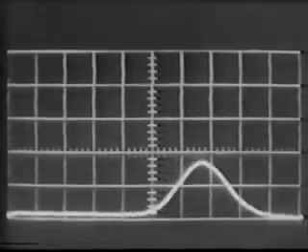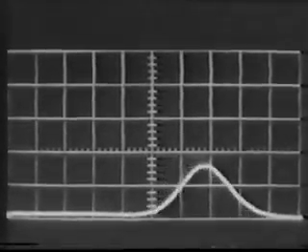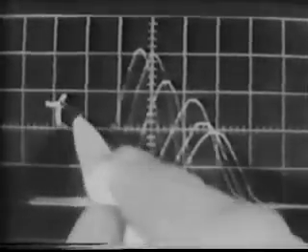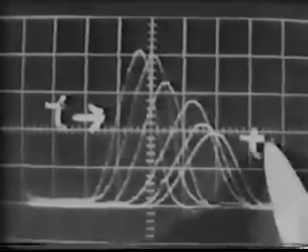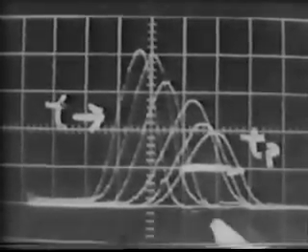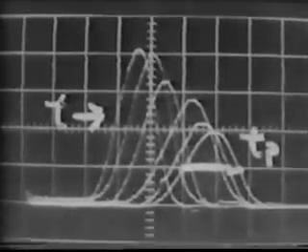To get the diffusion constant, we measure the width of the pulse as it moves out from the sweep origin in time t. For various delay times t, we measure the time duration, T sub p, of the pulse here, between points where the pulse height is half its peak value, corresponding to the half concentration value of Bell's formula. On this chart, we have plotted the values of T sub p squared as a function of the transit time t.